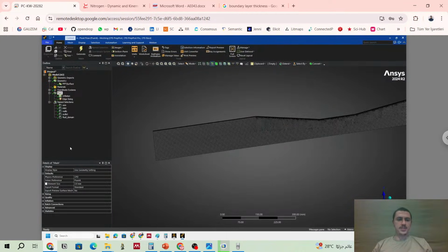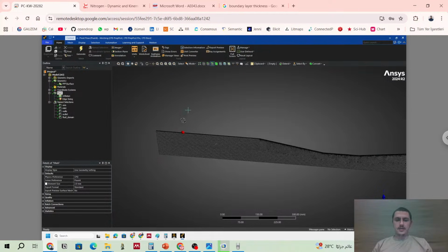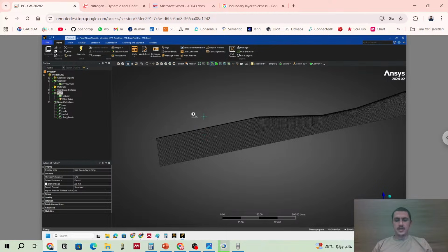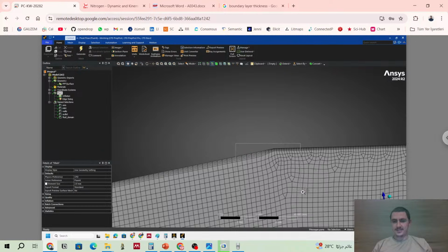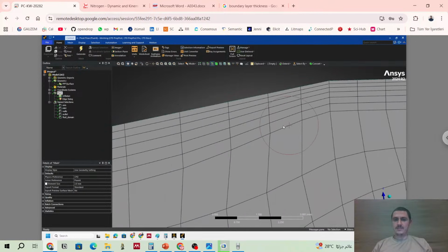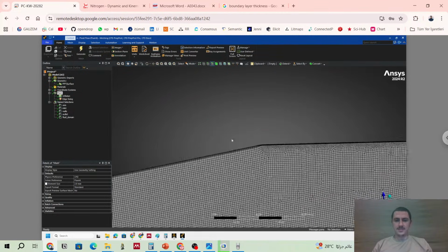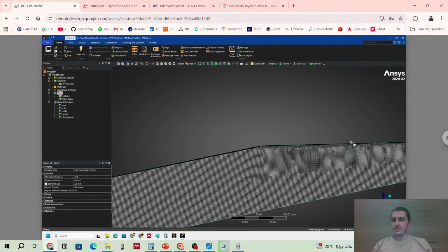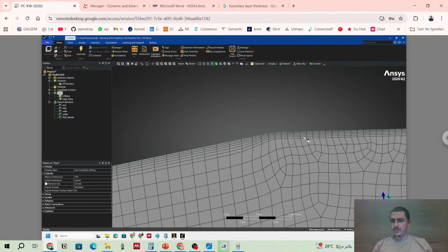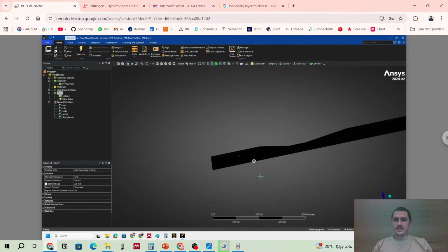Okay, I open the mesh. How many elements? The meshing part is, you see, I switch from one software and I just forget the shortcuts sometimes. We have the boundary layer, you see, more tiny. Okay, now I remembered how to do it. So you focus on the other part, like finer mesh, smaller than the others, as I want.